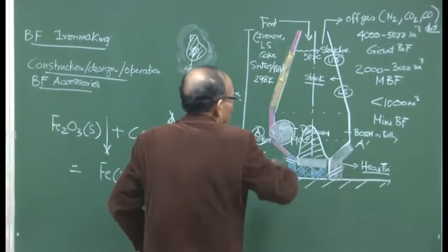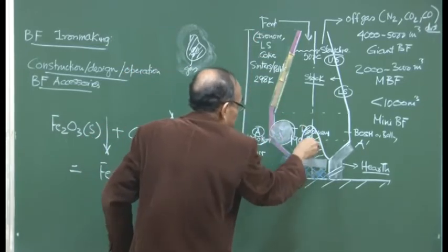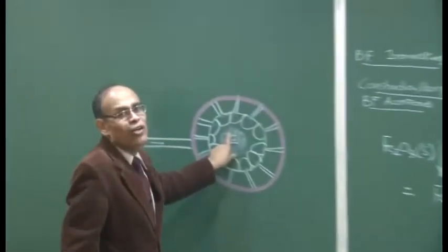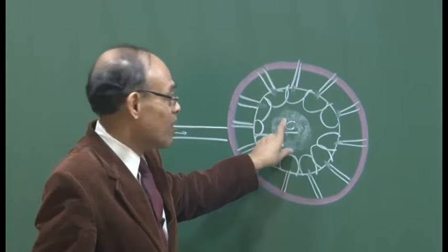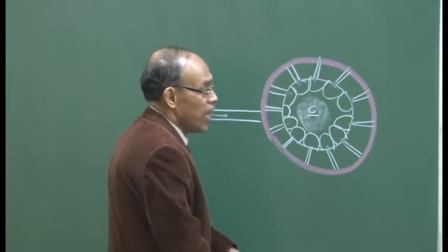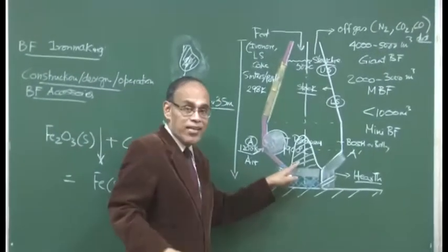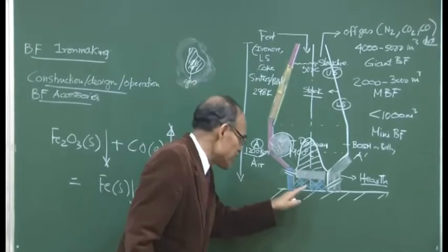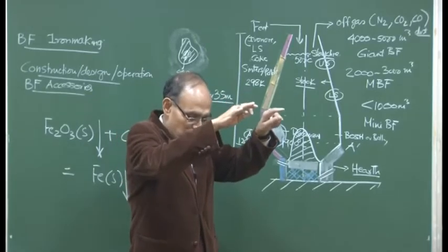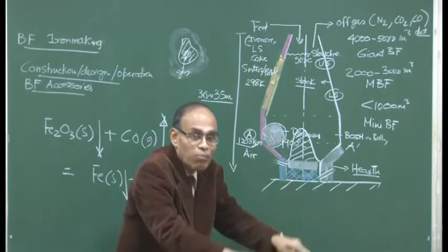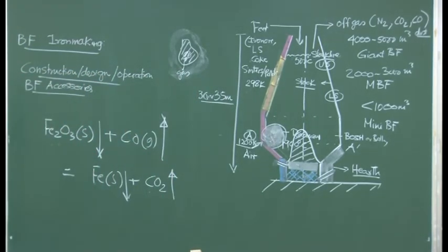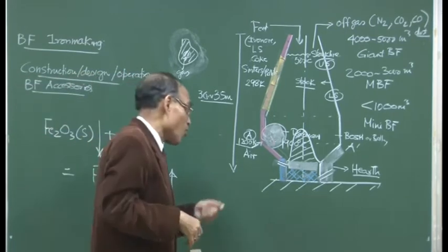That is the sectional view if you look from the top. So, you will see that this part is shown as the region where coke is there, and which is possibly undisturbed by the injected gas itself, because the gas is simply not able to penetrate up to the central region. And this coke is basically very light. Okay? It is much lighter than slag, it is much lighter than metal. So, it floats, and as the slag level and metal level go down, this layer also goes down. So, it makes this kind of movement within the blast furnace, depending on whether it is in the tapping phase or a non-tapping phase.